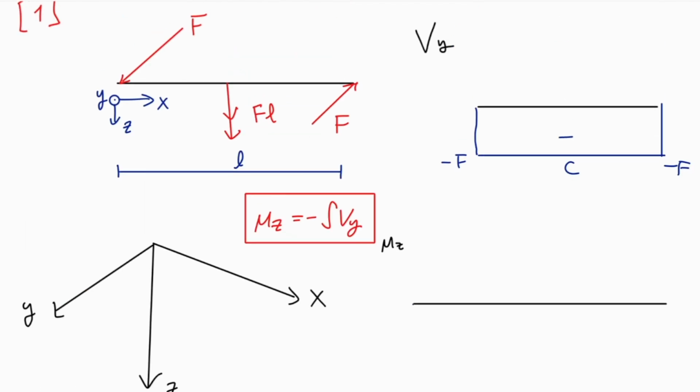So let's draw this now. There's no supports or anything, so I know I start at the 0 point. It's negative constant. We have Vy, which integrates to Mz. So this becomes a positive linear, very careful, positive, of minus F times the length that it crosses, L half. At L half, we have this point moment that I had to add in just for equilibrium reasons, and this point in the downwards direction.